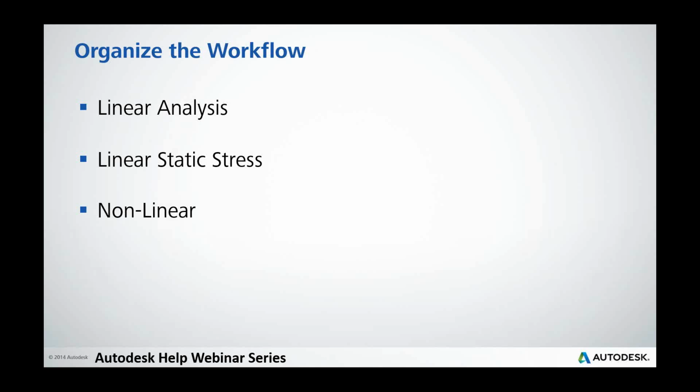There's some other information that we get that's really more of a qualitative result as opposed to a quantitative result. And then from there we can use that information and do a linear static stress analysis. And this will give us some of our stress output that we're interested in. And one of the things we're looking for there is material yielding, to see if we need to consider that.